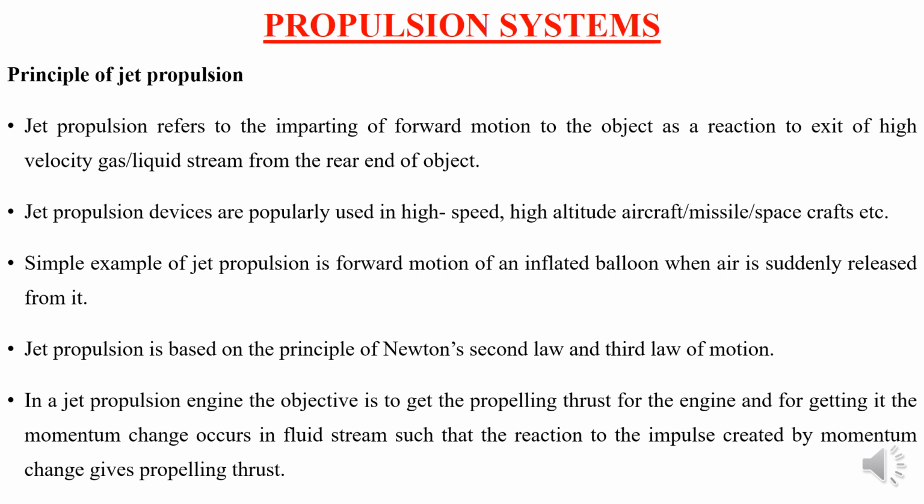How are you going to create that momentum? You are creating the momentum by burning the fuel, and you have to pressurize that fuel. So at constant pressure you are adding the fuel, so that it will burn in the gas turbine and expand. The pressure will remain constant because it is a constant pressure heat addition. Hence, high pressure exhaust gas will be there.